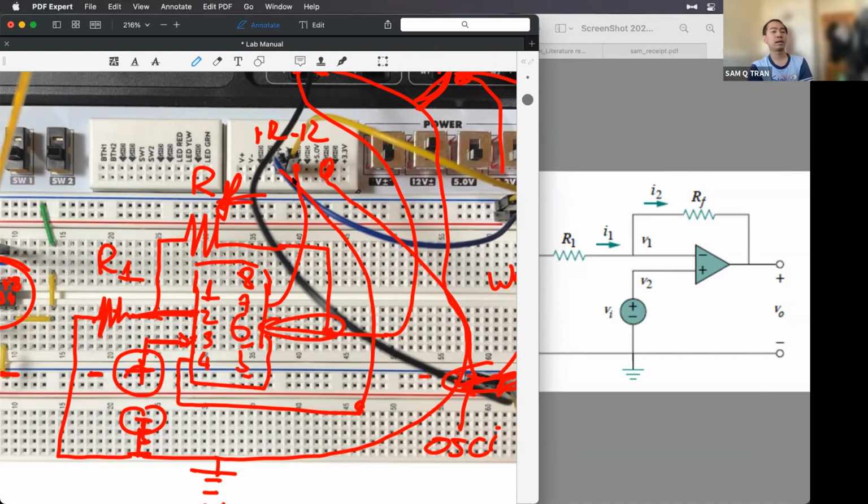And that's why when you do this experiment, there will be a step where, whenever you try to increase the ideal gain, the output voltage will be capped at 12 volt. So that's the idea of this experiment, to show you that you can indeed read the level of voltage saturation in real life. So, any more questions? I hope I answered your question.